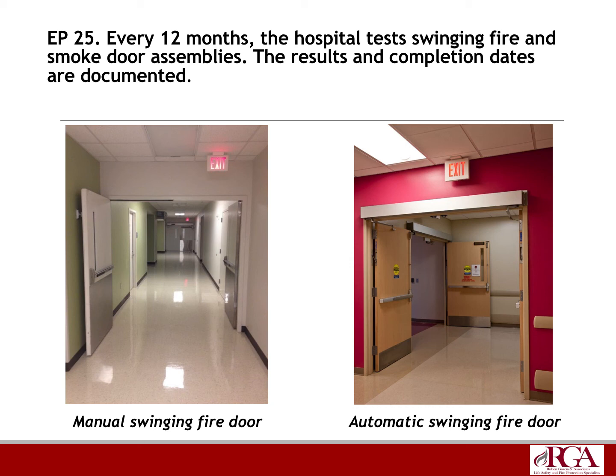So you pull the power off the header, off the operator, and then you pull off the end caps of the exit hardware or crash bars, and you pull off those respective power sources. Usually it's a little plug in there. Now you simulated fire conditions. Whether or not that actually happens during a fire alarm condition needs to be checked by the fire alarm vendor. That's why it's kind of good to have that integrated testing.